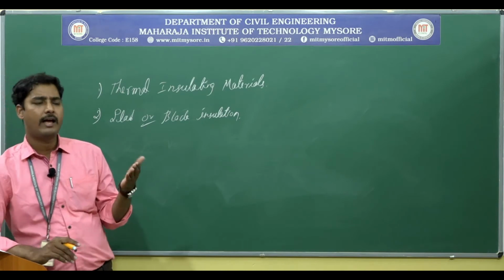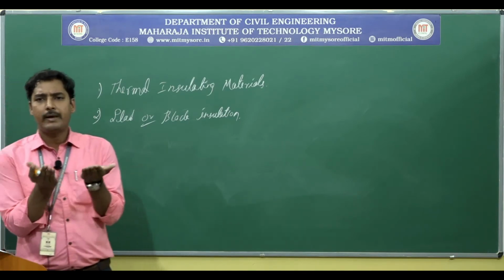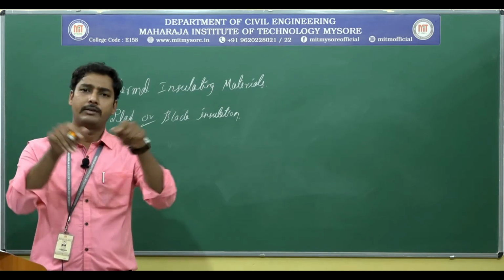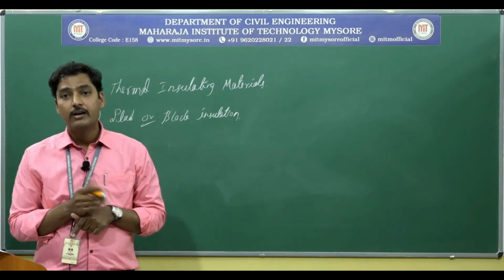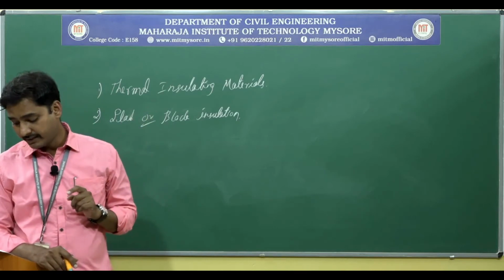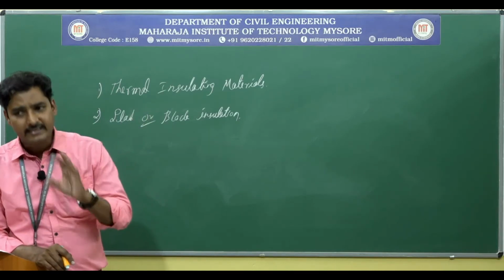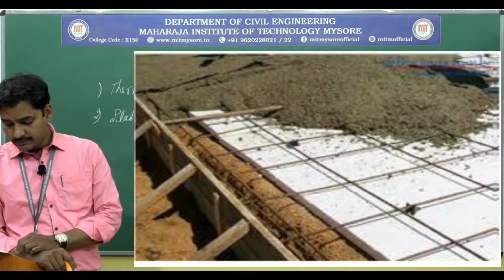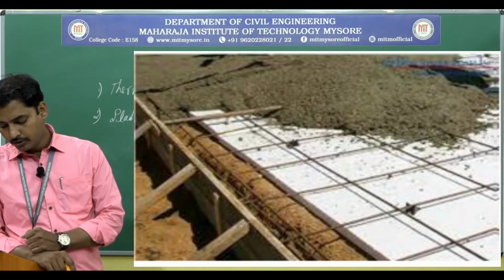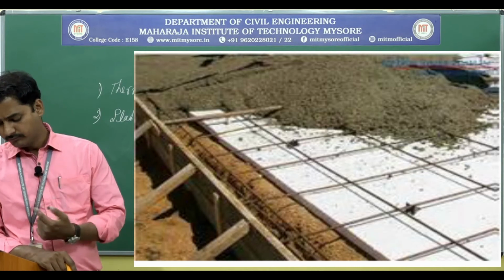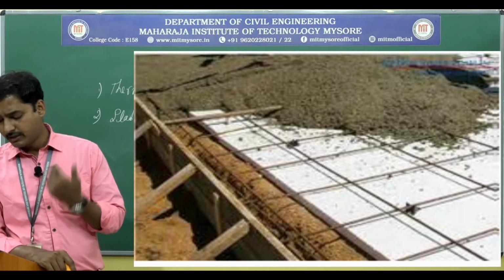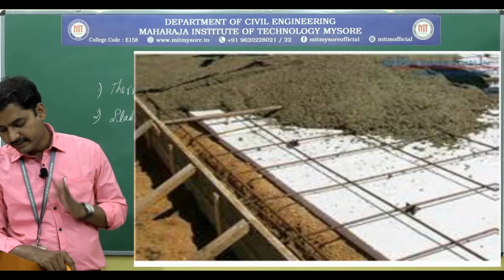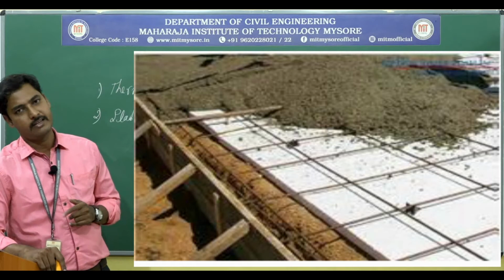Even we need to join those panels, one over the other, depending upon the requirement and the area to be insulated. Especially these types of insulation techniques are preferably good in RCC slabs. You can observe in this figure, these may be made of cork board or mineral wool or cellular glass or cellular rubber, sawdust, asbestos cement, etc. And these are fixed to walls, slabs as well as roofs.